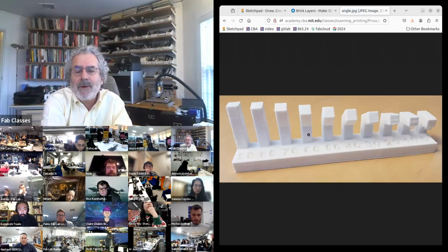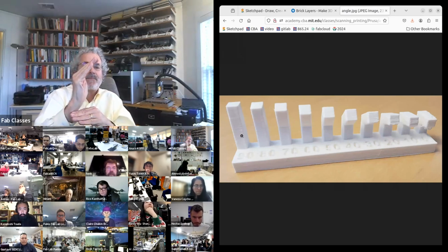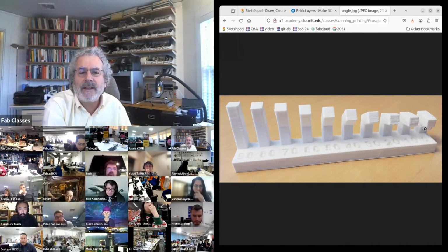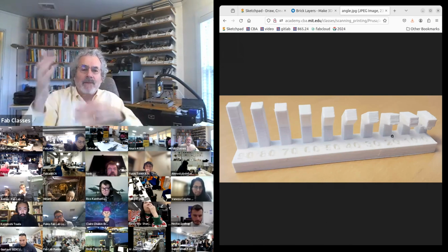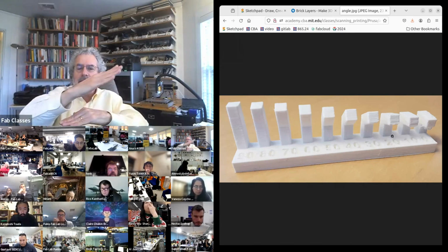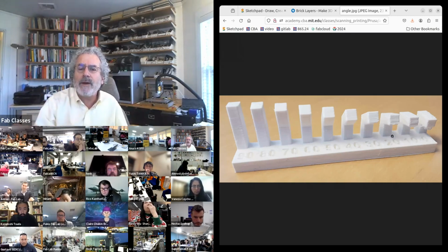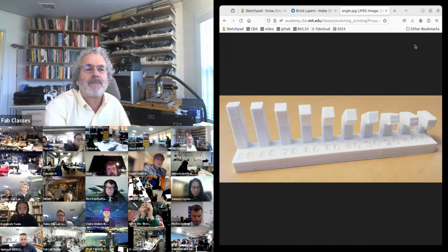So this is the most important design rule. What I'm doing here is I'm stepping an angle. And you see vertical is fine. If I try to print horizontally, I get spaghetti underneath. But around about 20 degrees, it's happy. As long as you have a little bit of an angle, like 20 degrees, you can keep building out even though there's no supports. So this is one of the ways you eliminate the need for supports, is rather than flat overhangs, you have angled overhangs.